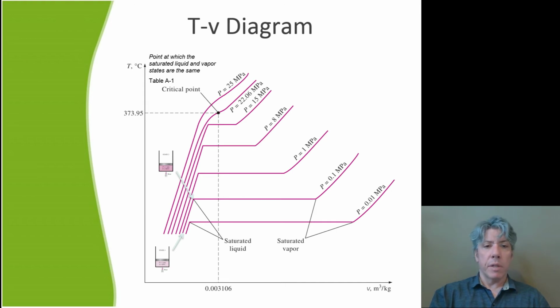that I have, though it's not really a boiler. Anyway, that water is going to expand, and if I didn't have an expansion tank that could accommodate the extra volume, well, either the tanks are going to give or the piping is going to give, something's going to give, because that water is going to expand. And so I had to take that expansion into consideration, even though my system's called a boiler, but it doesn't boil the water, it just changes the temperature of the water from subcooled, not even up to the saturated point. But the water volume is going to change as the temperature changes.